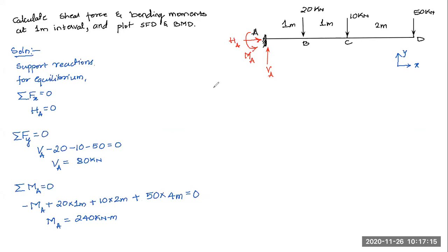So first we'll go for calculating shear force here. We used to take a section and move the section by the given interval, right? Normally we took the section from the left end and started moving towards the right end of the beam. Now in case of cantilevers, it will be a little easier if you place your section towards the right, if I start from the right end of the beam. That is the advantage for us. It will be simpler to calculate the shear force and bending moment.